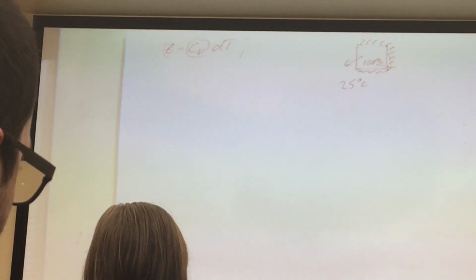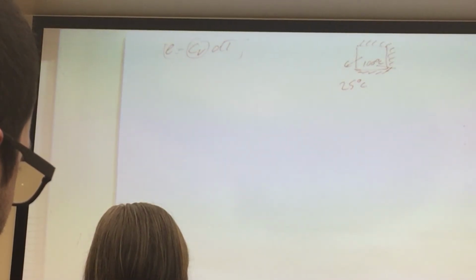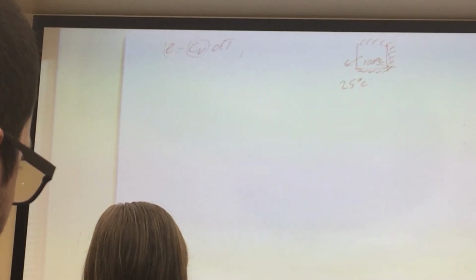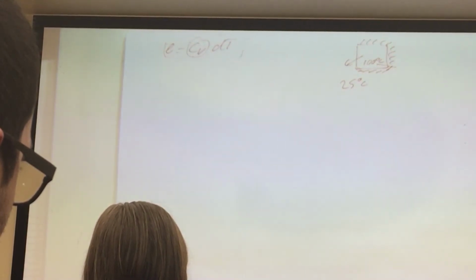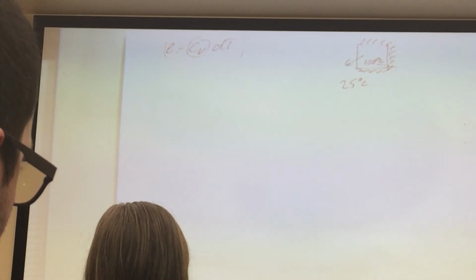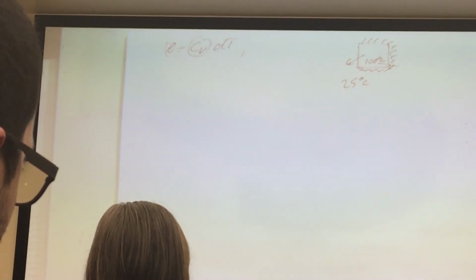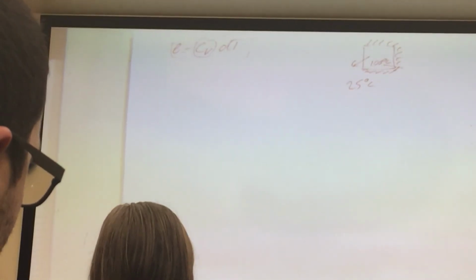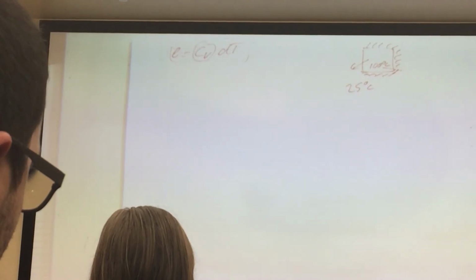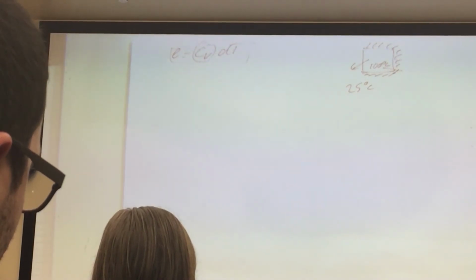And this is, again, like I mentioned, if I have a large temperature gradient from 3000 in a combustor all the way to ambient temperature conditions, which is 300 Kelvin, well, that's a massive temperature gradient. I can't assume CP to be constant. I have to vary it, and gamma as well. You work with high-speed aero. We've always taken gamma 1.4. However, 1.4 changes quite a bit in the engine. That changes your thrust overall calculations. So I'll account for that.